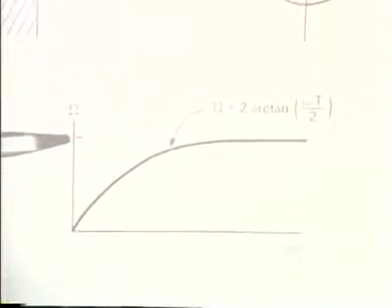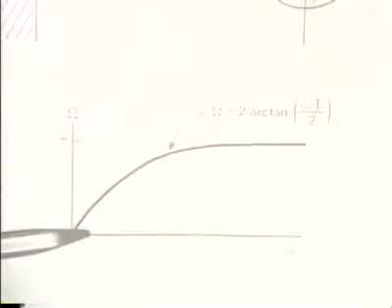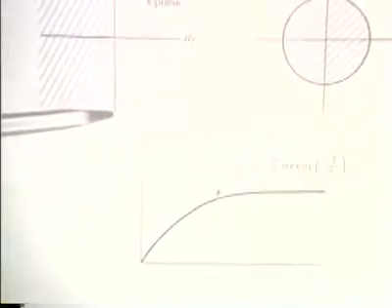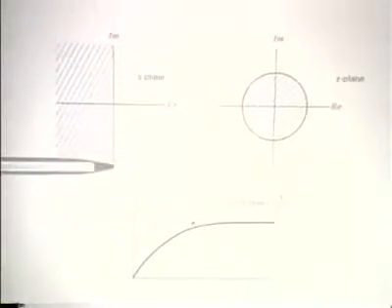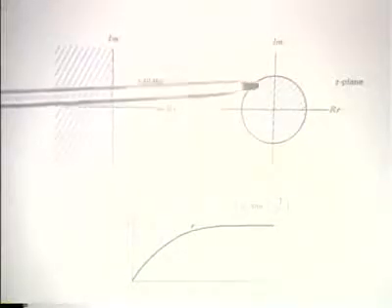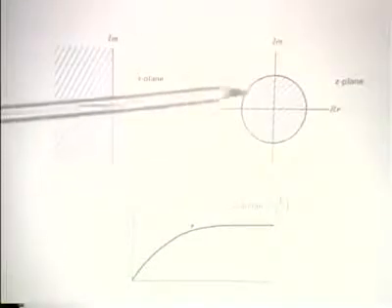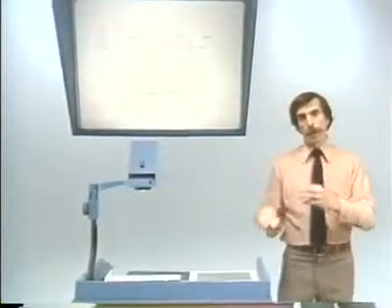And what this corresponds to then is a mapping of the j omega axis, or continuous time frequency, to discrete time frequency. And if we think more generally of the mapping represented by the bilinear transformation in the context of the S-plane and the Z-plane, it corresponds to mapping the j omega axis in the S-plane to once around the unit circle in the Z-plane. And you can also convince yourself that the left half of the S-plane maps to the inside of the unit circle. And so that means that stable continuous time filters will always map to stable discrete time filters, which is exactly what we desire.